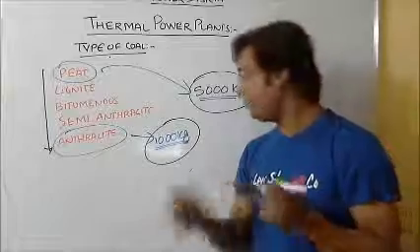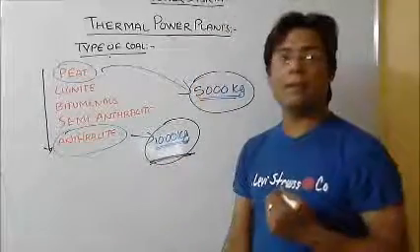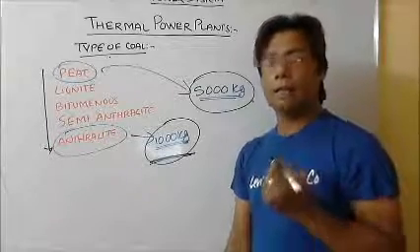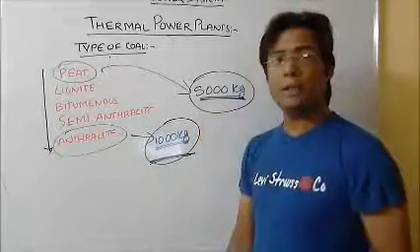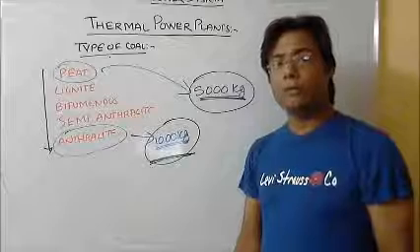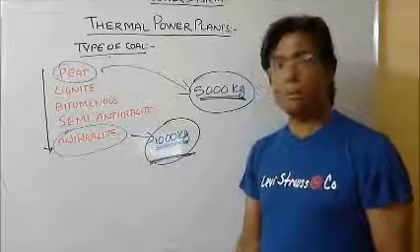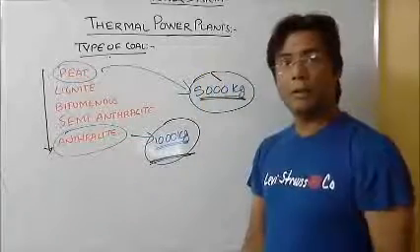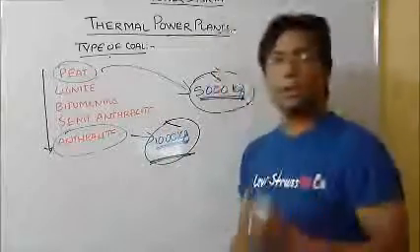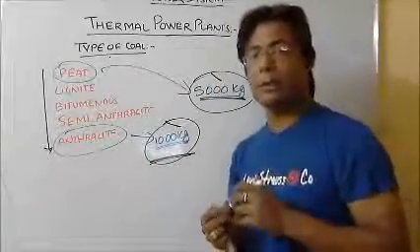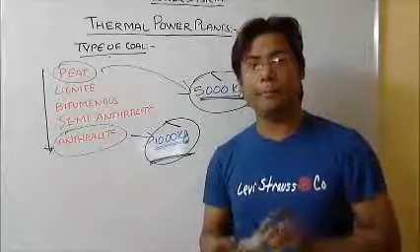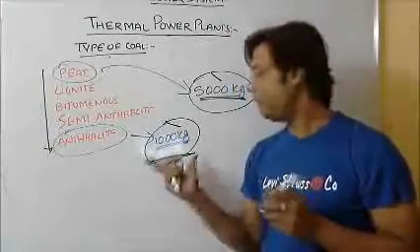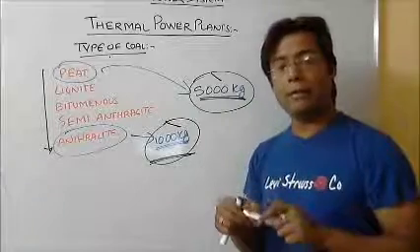So to take 1000 kg of anthracite to the station would be cheaper than carrying 5000 kg of the peat. One thing which is very important in case of thermal power station is the transportation of the fuel also, because 5000 kg will be transported at a higher cost, whereas 1000 kg will be transported at a lower cost. One more thing comes now: since anthracite is 1000 kg, when it is stored in the coal storage plant, it will take very little space.